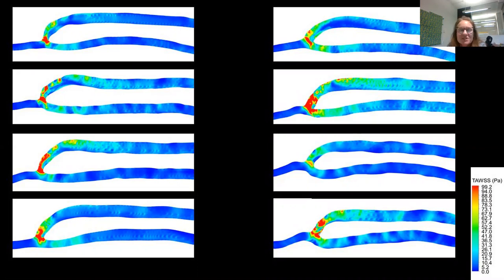Okay. Gotcha. It's interesting that we've been looking at this particularly with the stent recreation from the micro CT at the moment, in that when we segment a geometry, we do it in slices. And so you do end up with this kind of waviness, which is what you've pointed out here. It's how much do we smooth it and how much do we keep that kind of roughness to get a bit of realism in there. And so we've been looking at that a lot with the stent recreation. And we actually went back to Abbott and said, what is the surface roughness of the stent strut so that we can segment it to an appropriate level.